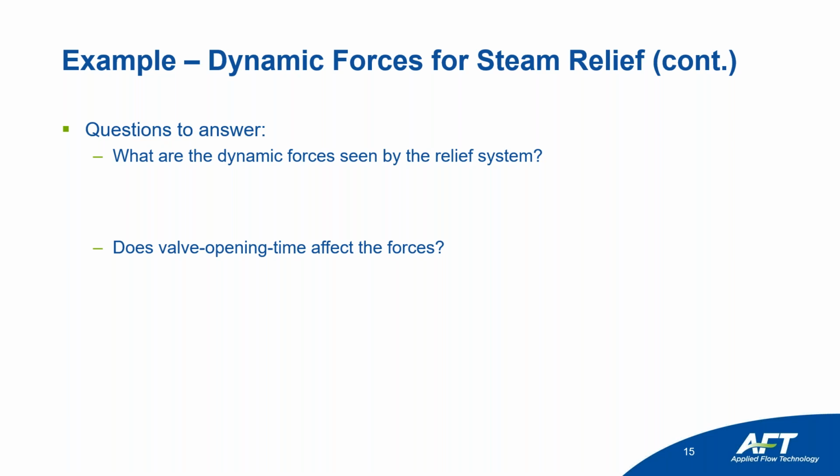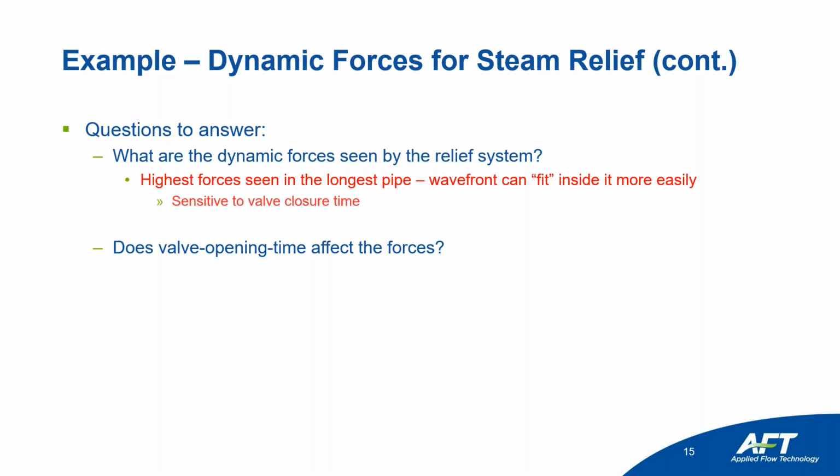We had 2 questions to answer. What are the dynamic forces seen by the release system? The highest force is seen in the longest pipe. The wavefront can fit in that, right? It is sensitive to valve closure time though, so that answers my second question.